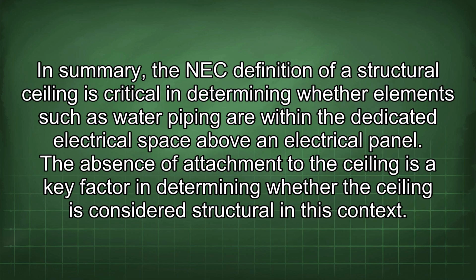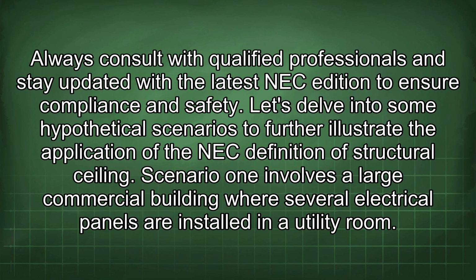In summary, the NEC definition of a structural ceiling is critical in determining whether elements such as water piping are within the dedicated electrical space above an electrical panel. The absence of attachment to the ceiling is a key factor in determining whether the ceiling is considered structural in this context. Always consult with qualified professionals and stay updated with the latest NEC edition to ensure compliance and safety.